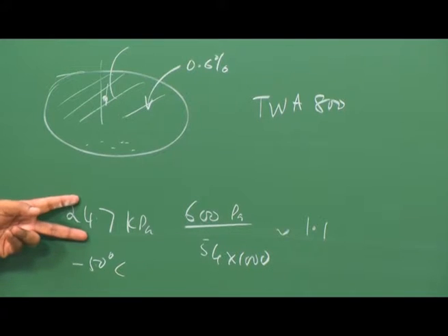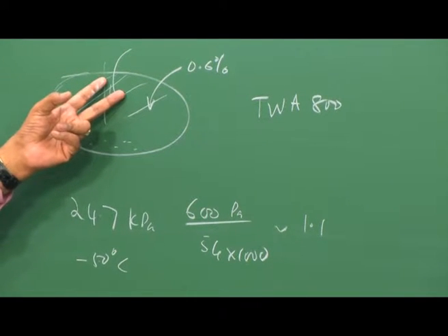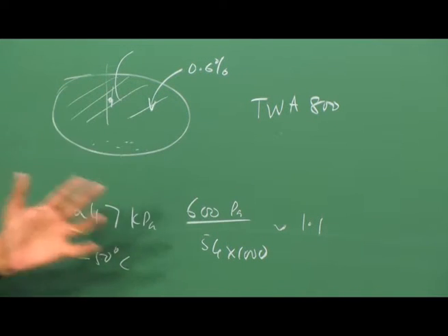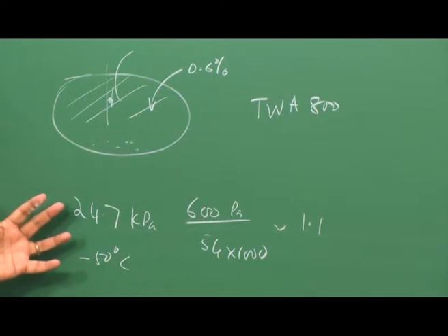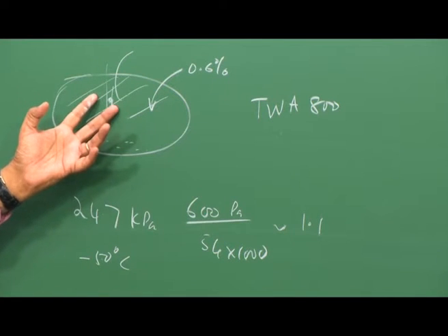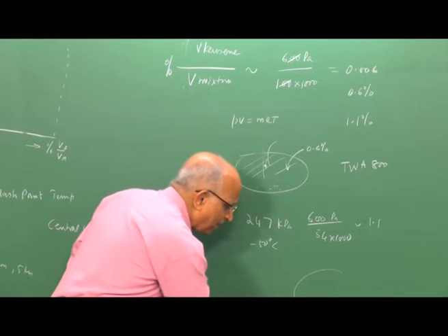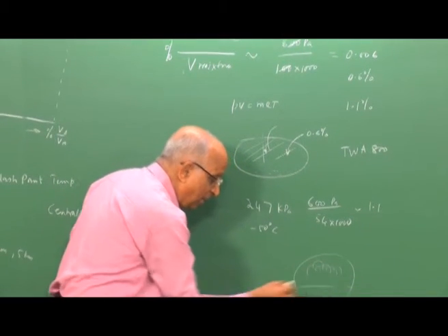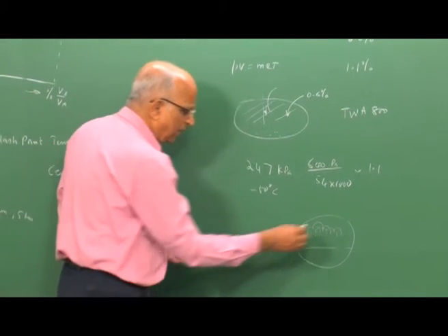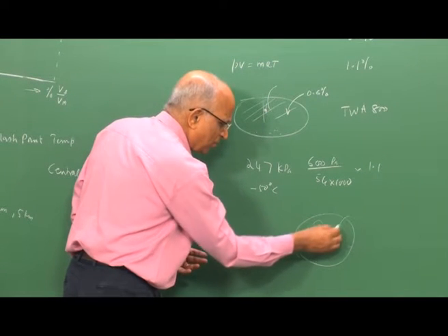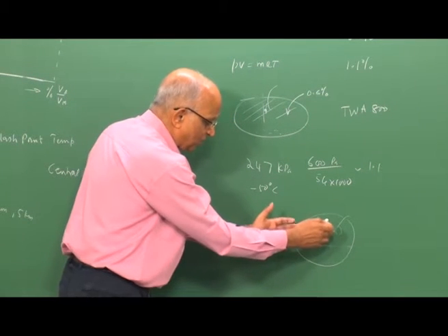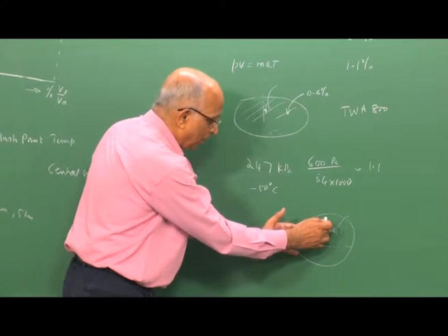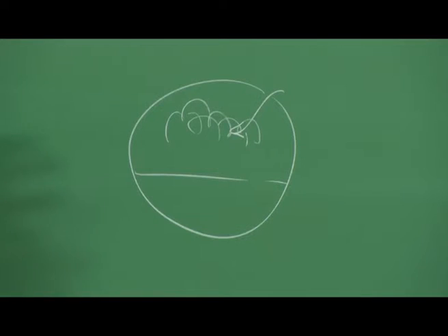The thing is, yes, we are talking of fuel tanks being subjected to low pressure, and therefore, one of the recommendations was to be able to put some inert agents. That means, let us say I have a fuel tank, I could have a mixture which is combustible, it is within the limits of flammability. The recommendation to avoid such accidents was, can I use some inert gases which I put into the vapor mixture, such that I bring down the quantity of the fuel which is available.